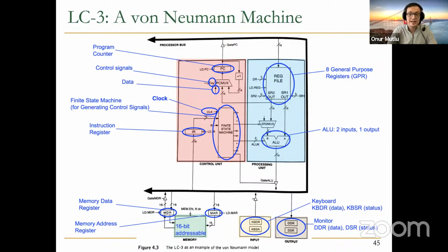And we've seen essentially all components over here: registers, muxes. This is an adder, as you can see, +1, incrementer, etc. And we will see more in detail. Okay, there's the ALU operation, as I mentioned. It comes as an output of this finite state machine that decodes the instruction and generates a control signal. So if it's an add operation, this ALUK signal will be asserted appropriately to enable an add operation in the ALU. If it's AND, then it will be signified appropriately, etc.